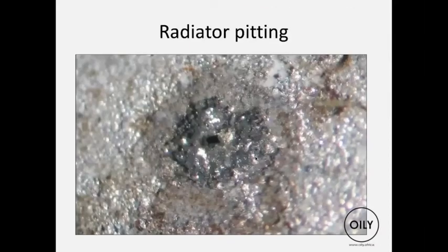That is a pinhole in a radiator. That pinhole developed in 2 weeks of operation. That radiator had been in service for 2 weeks. And they had antifreeze in the system, but they'd mixed antifreezes. And the two antifreezes were not compatible with each other. They reacted and formed an acid, and the acid ate through the radiator.